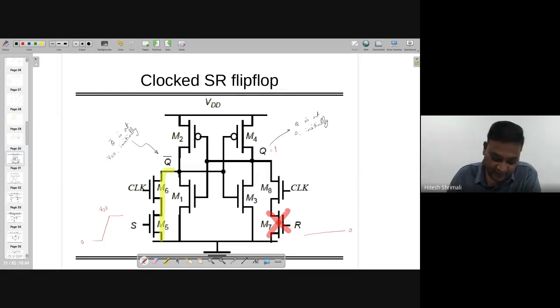So what is happening over here, when it's VDD, to go to 0, it takes at least some time, which is traveling from this point, going from here to here. It will take the propagation delay coming from these transistors M5 and M6 and the node capacitance over here, on both sides.